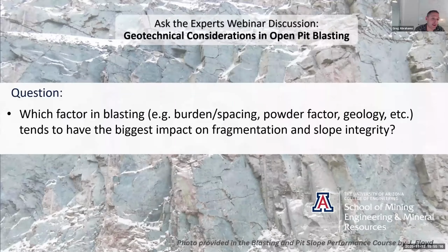In which case, there's going to be trim blasting and pre-splitting, and confinement is a big one. It's spoken about in different ways, whether we talk about face burden, but the confinement of the shot, how much energy, how can we move the muck out of the face and not hit the wall?